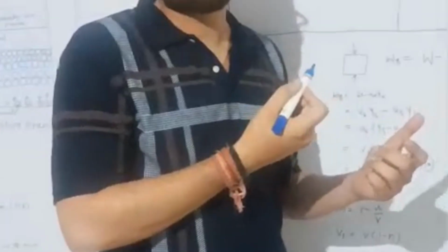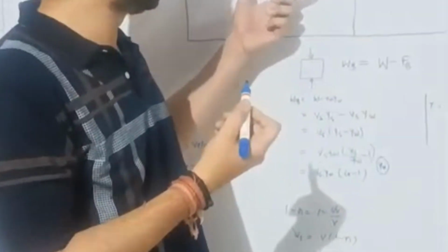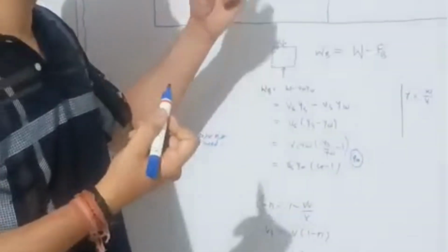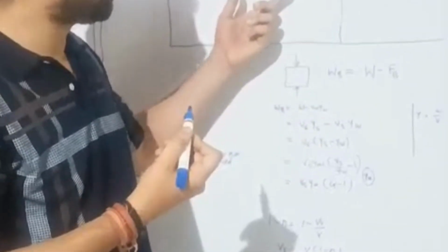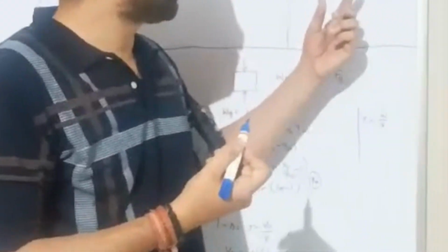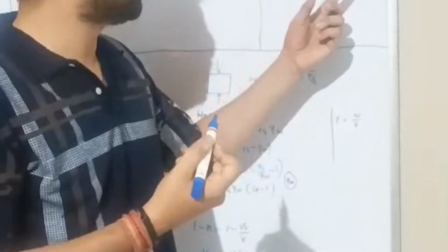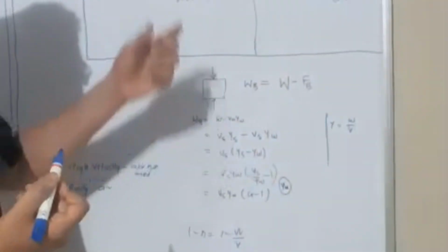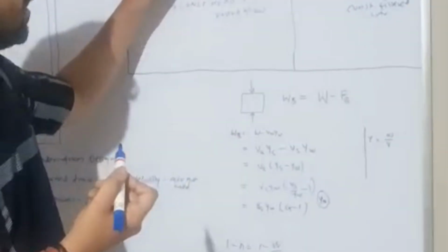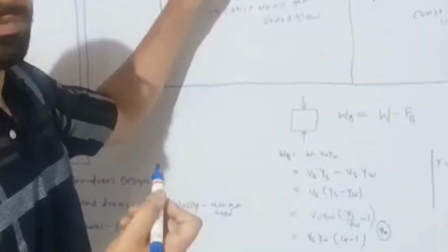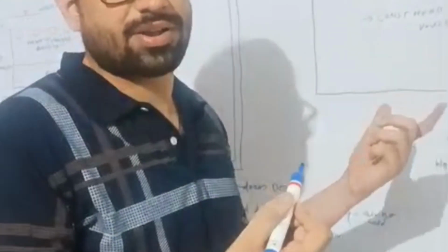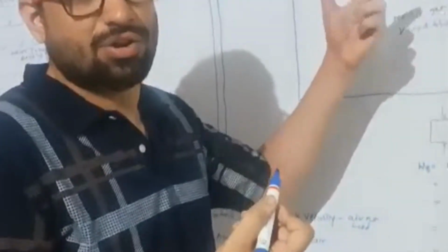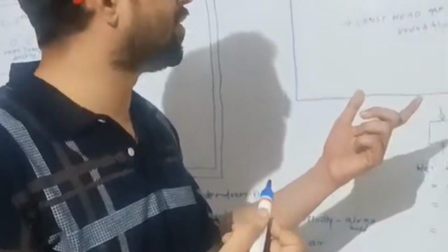In these two types, first we have constant head and get a varied flow. The second option is to vary the head to get constant filtered water. Over the filter media, the water head is constant. Generally 1 meter to 1.2 meter is preferred over the filter media as the head required to sieve the water through the filter media.